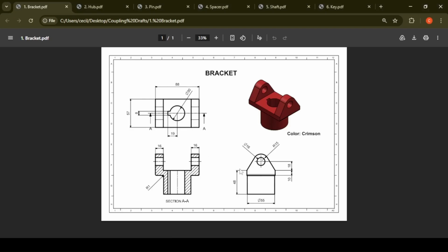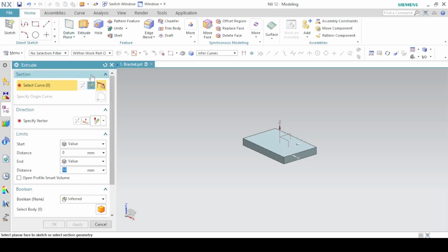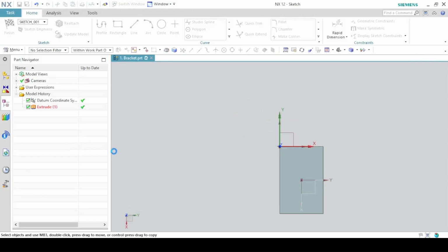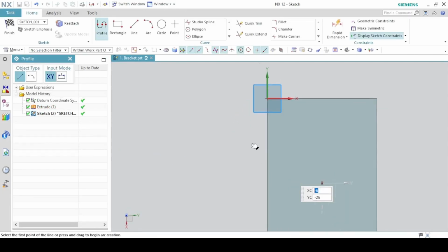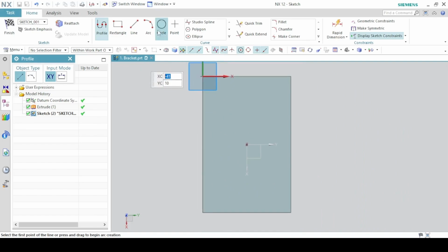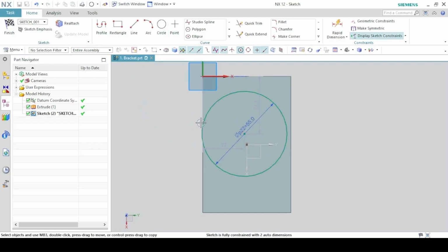Next, we add the base cylinder. It starts on this edge of the rectangle, so on this face here, and we extrude down by a distance of 48, and the diameter is 55 millimeters. So again, extrude, sketch section, click on this face. Okay. We add a circle of diameter 55 millimeters. The circle should be in the middle of the rectangle.